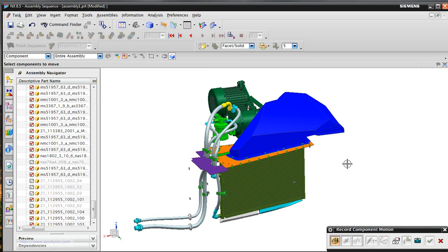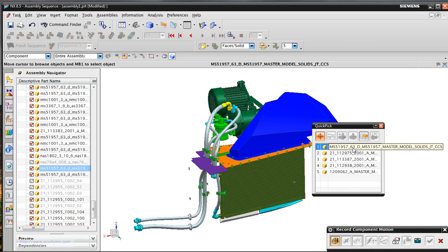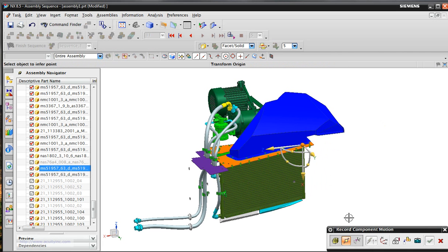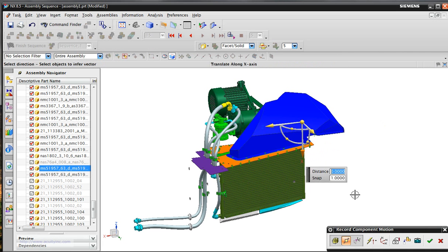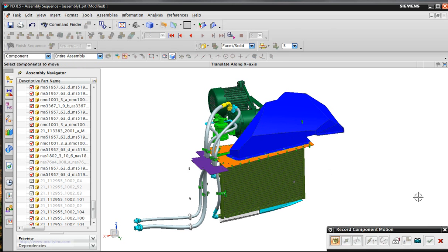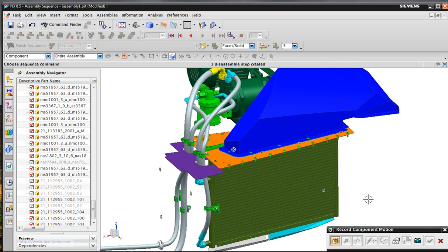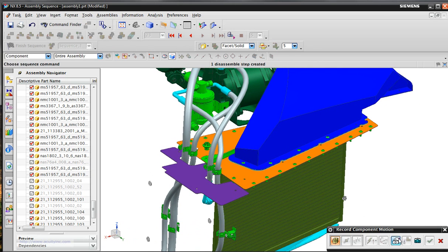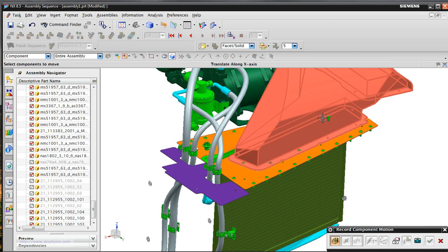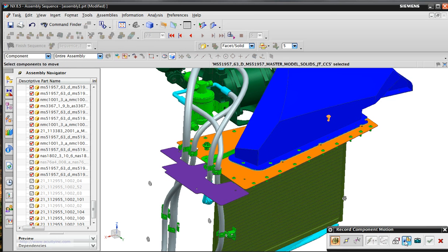Then we'll pick the insert motion command, and you notice you get a little toolbar up there. So the method is you select an object, you pick what you want to do. In this case, we're going to move it. And if you've made a motion, you want to apply the motion, and then pick the object again, and we use the disassemble command to get rid of it. So one more time, record the camera. Pick the object, there's the move it someplace to show it's assembled. Go ahead and select it again, disassemble it, and repeat for the other objects.